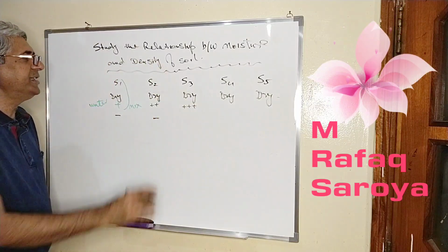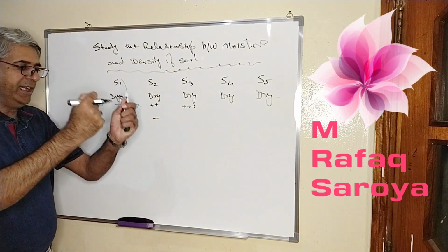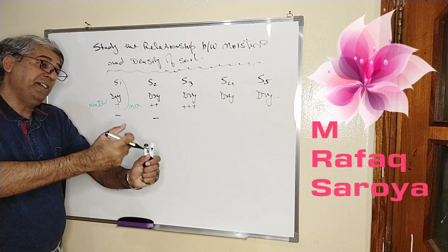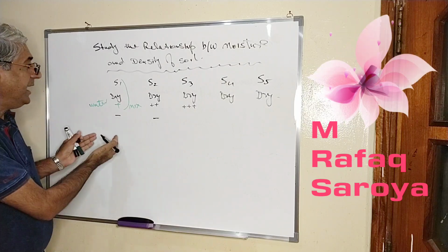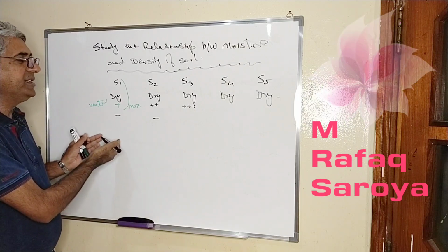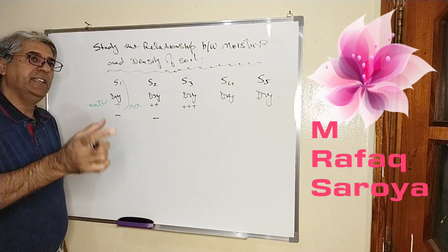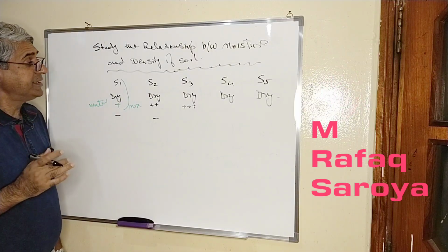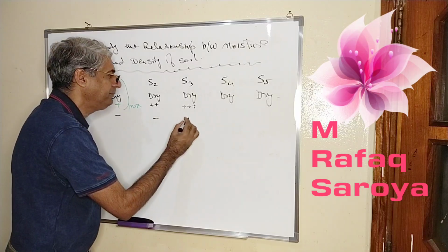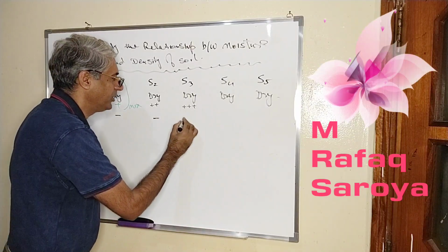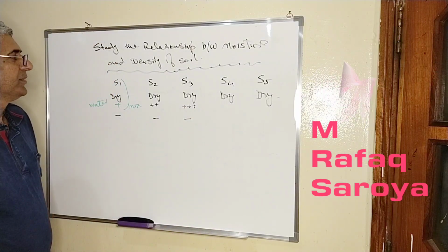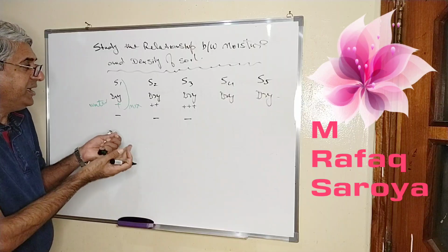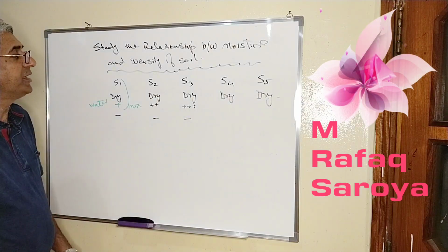I have increased the amount of water and I am mixing it very well. After mixing, same procedure which I told you in my step 1: 5 layers, and each layer is compacted by 56 blows, and then after doing all this practice, I will find out its mass. I will tell you later in the example, its mass will go on increasing up to a certain limit.